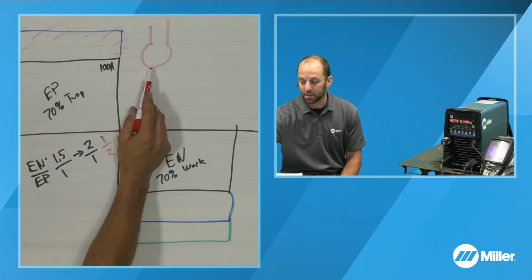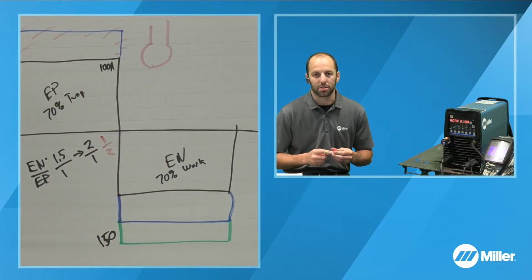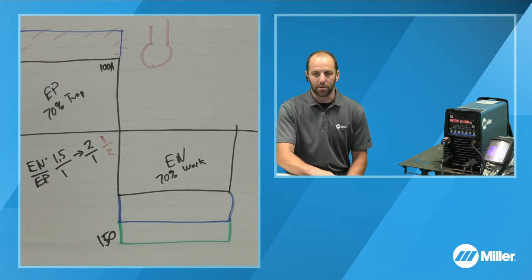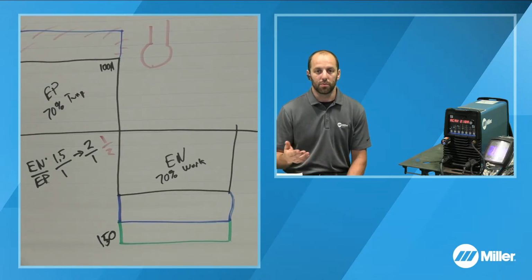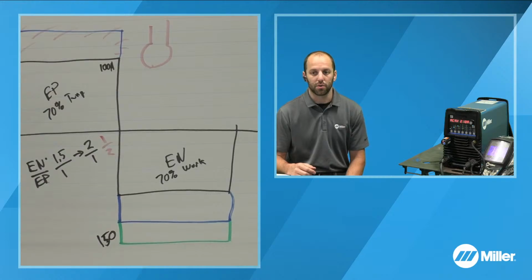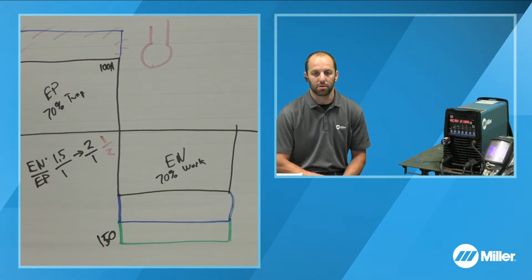going to do is give a significant amount of heat up onto this tungsten and definitely cause a balling effect during the weld that could lead to tungsten erosion and ultimately tungsten inclusions in the weld, which would lead to welding discontinuities. And according to many codes and specs, those tungsten inclusions would be rejections during some sort of an X-ray process.